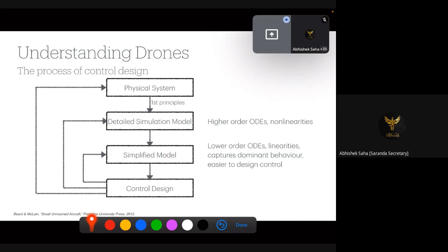For example, let's say a quadrotor is going to move, but it is not highly maneuverable, which means the attitude changes won't be much. The attitudes would remain within 0 to let's say 30 degrees for roll, 0 to 30 degrees for pitch, and the yaw angle would not vary much. Usually the nonlinearity comes from the roll and pitch angles. Now, if you assume that these angles are going to be restricted within -30 to +30, then these are basically the small angle approximations that can be used.